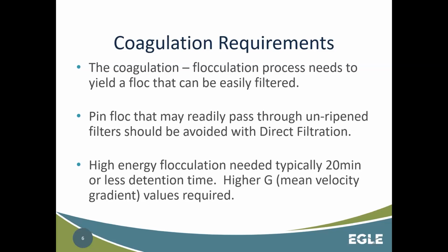Then I guess one key concept to remember, and I believe this was talked about in the coagulation presentation earlier, but if you remember how media filtration works, it's through a process of particle attachment. It's not straining.